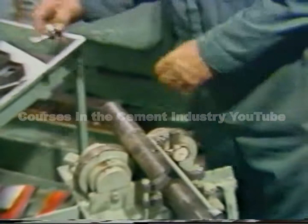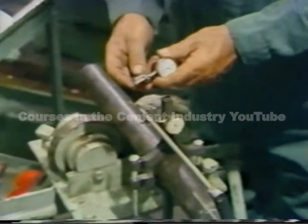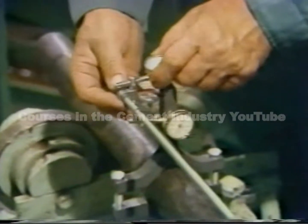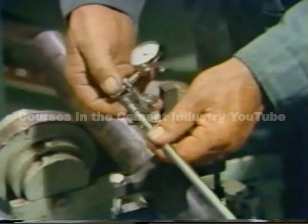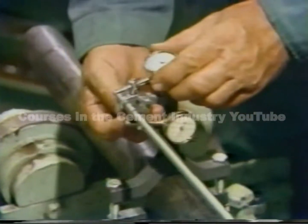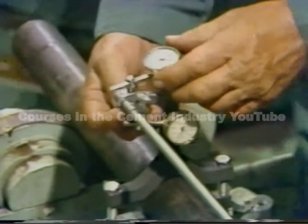The second dial indicator will be used to measure parallel or offset misalignment, so it has to be mounted with the plunger resting on the top of the post. It's important to take the time to make sure that the dials are positioned properly and that they're good and rigid.